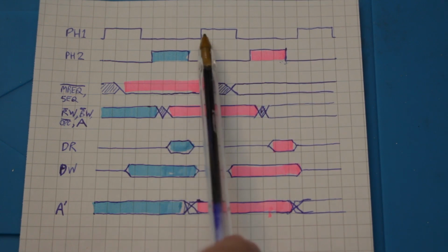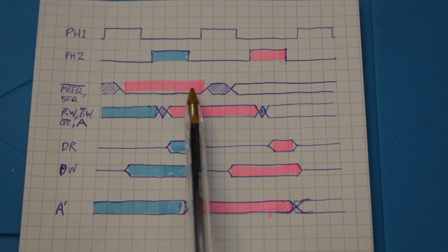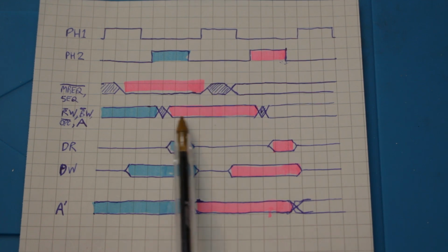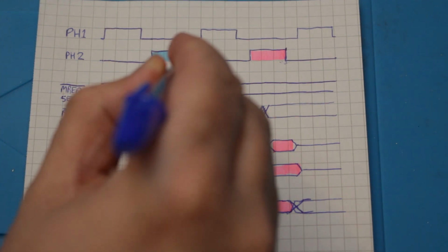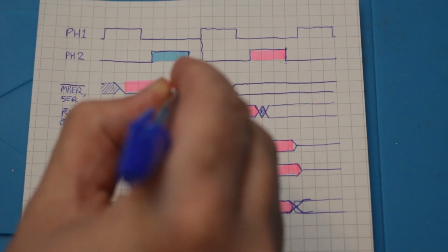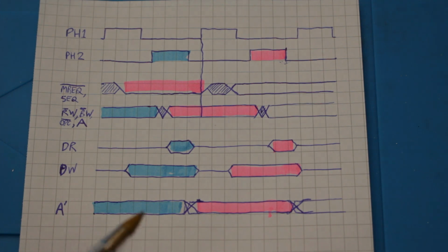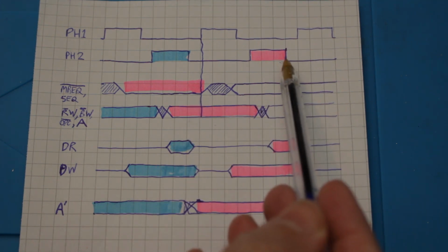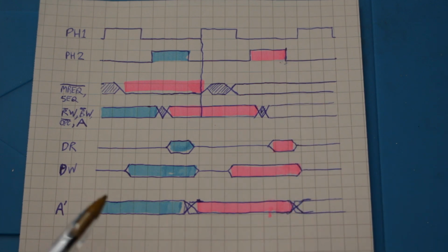The falling edge of phi 2 or the rising edge of phi 1 might be good times to latch the memory request line. And in fact, if I'm latching anything at that point, I might as well latch the read, write and byte word lines as well at that stage. So I think that's probably what we should do. Take the rising edge of phi 1, use that to latch all of these, and then just remember that, carry them forwards until the trailing edge of phi 2, when we're going to be done with all of our reading and writing at that stage.